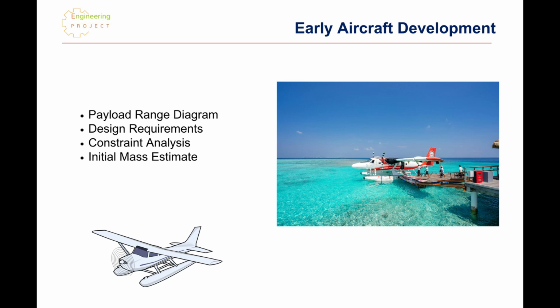The first progression of our Capstone project is the early aircraft development. Here, before starting our aircraft, we consider the design requirement, construct a payload range diagram, then do constraint analysis, and lastly initial mass estimation.